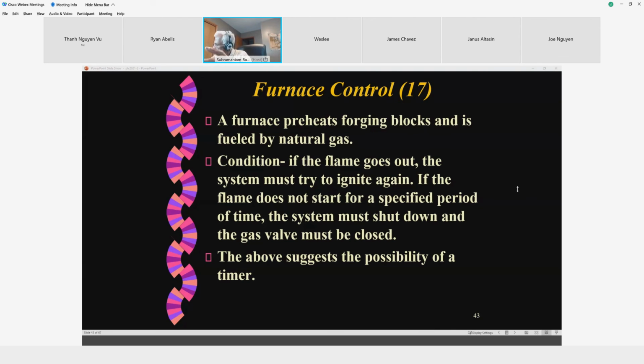It's like the spark plug technology for car engines. Okay? So when it ignites, good. It switches off the electronic ignition because why? There is no need. Your ignition has come on. But there is a flame sensor which is looking at the flame to make sure that the flame is sustained during the time when your condenser is heating, right?